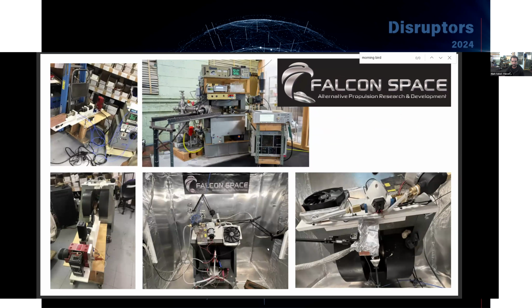Over here, these are just a few of the different test setups that we've tried with this experiment. On the bottom right, we have the X-band setup that's inside of our Faraday cage. Instead of a waveguide, it was going into a cone, a horn antenna. In the center, we have one with a waveguide.